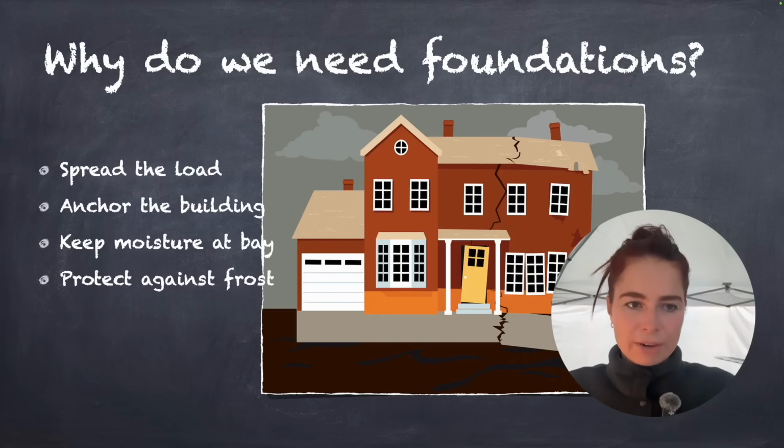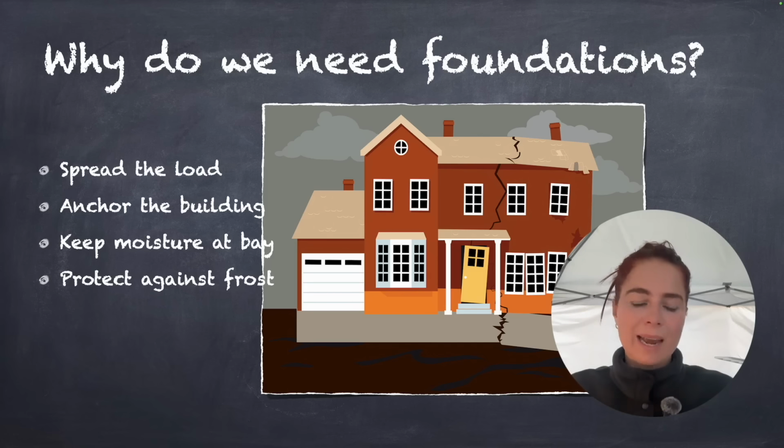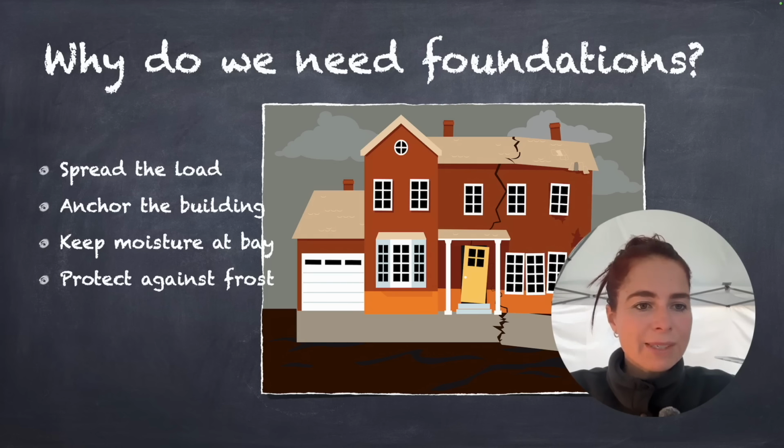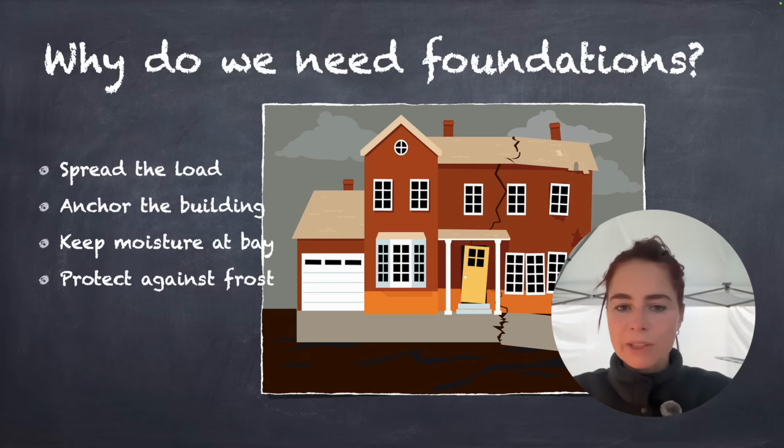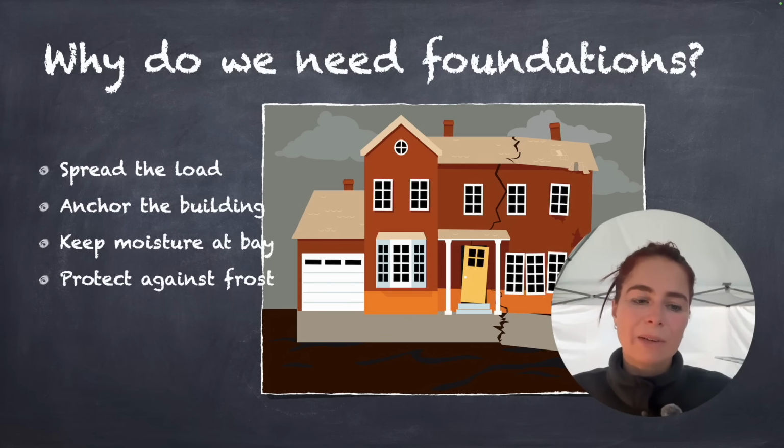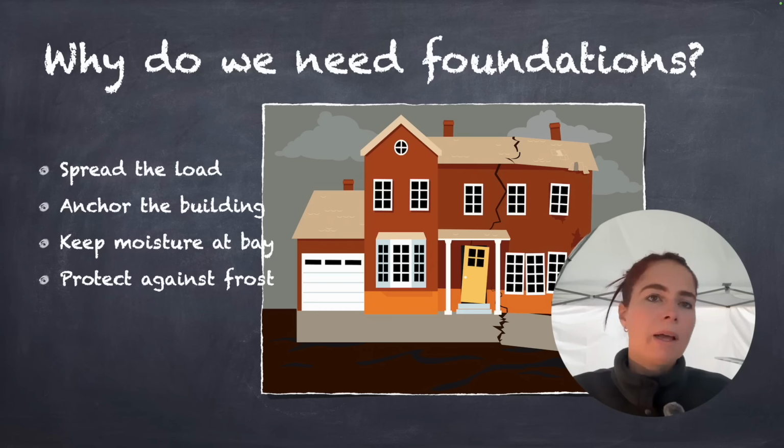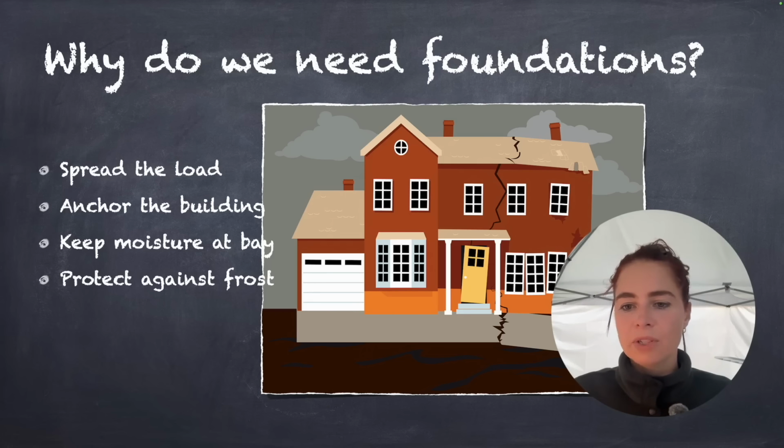What are foundations is the first thing I'm going to ask, and then also why do we need them? The foundation is basically just the part of the building that connects the building to the ground. Super simple. So what do they do? One of the main things they do is they spread the load of the building. You've got a roof and walls and furniture and people, all of this stuff that's pretty heavy. And so that foundation is going to spread the weight over enough soil so that the house doesn't sink or tilt.